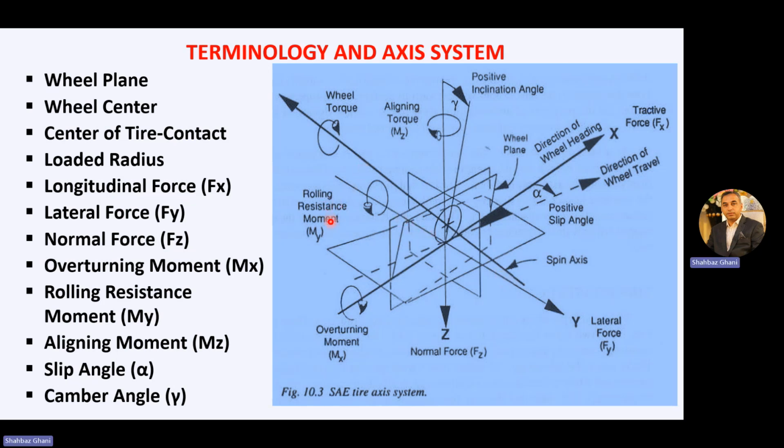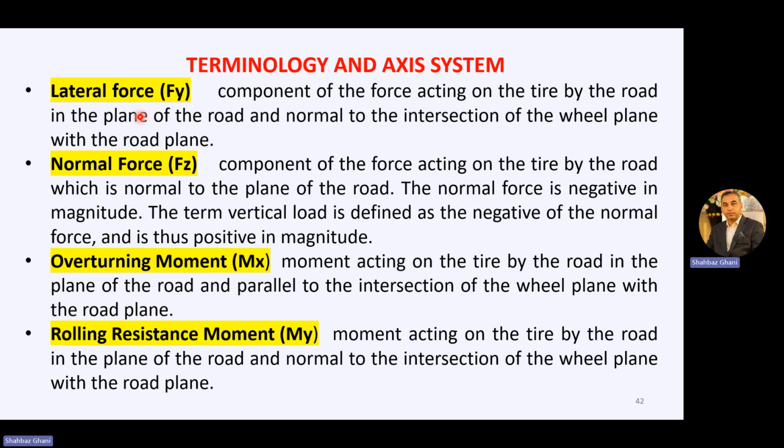So rolling resistance moment, this is your lateral force. Normal force, which is acting normal to the plane, component of the forces acting on the tire by the road which is normal to the plane of the road. The normal force is negative in magnitude. The term vertical load is defined as the negative of the normal force and is thus positive in magnitude.